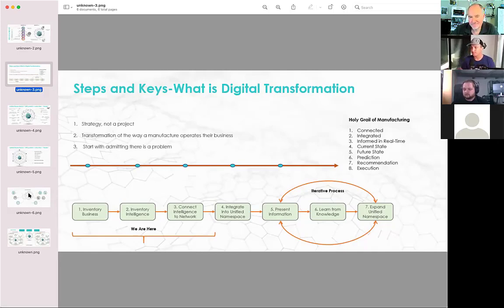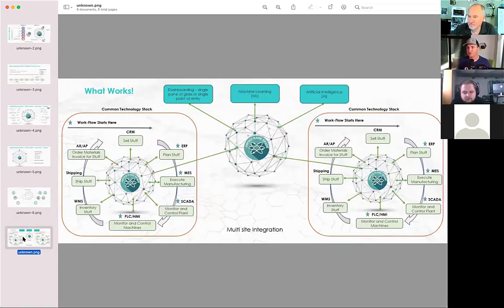So I do want to show this last slide here. This is kind of like a little bonus. I talked a little bit earlier about your Ignition gateway, especially because it's using OPC UA to talk to your PLCs, it's really set up as your edge device, so this would kind of be your local unified namespace. This would be your Ignition gateway right here.